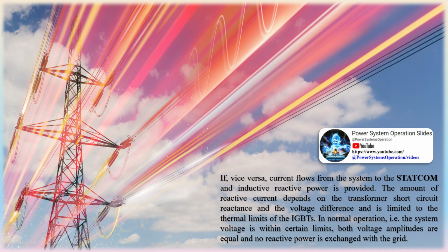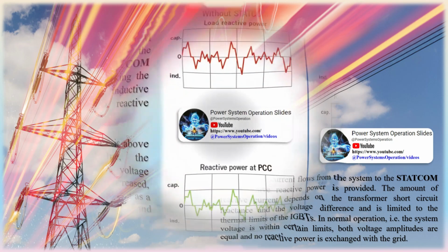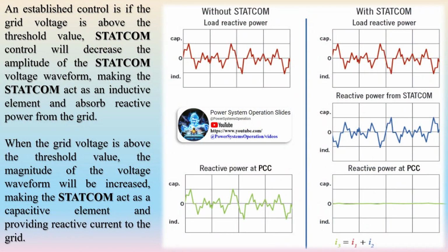Unlike synchronous compensators, STATCOMs have no mechanical inertia, allowing them to respond much faster to changing system conditions. They do not contribute to short-circuit currents and have no moving parts. They also possess a symmetric lead-lag capability and can theoretically switch from full lag to full lead within a fraction of a cycle. Numerous research papers have demonstrated the crucial role of energy storage systems (ESS) in power system control.